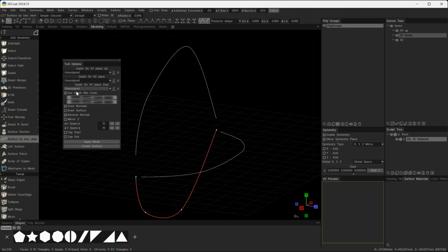I'm just showing how these relate. So let's start with this one. There are 2 ways we can do this. We can either use this little pick icon here. Click on that pick icon, you can see my cursor changes, and then I can click on that particular curve. Or I can just use the drop down box here as well to select those curves.